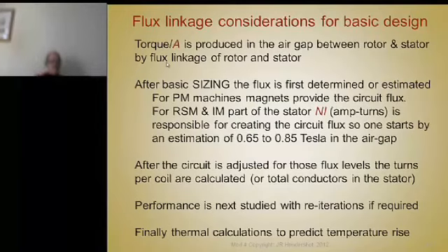So now you've got to adjust the circuit to carry that flux for all these 3 machines by figuring out what the cross sections are, and you have to balance that with the cross section you have available for copper, because once you know what the ampere turns are, you know what the current is, how many turns, how much space you've got, and what the current density is.